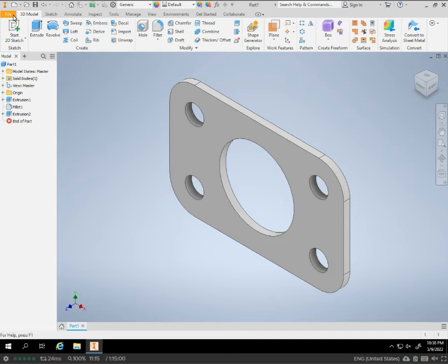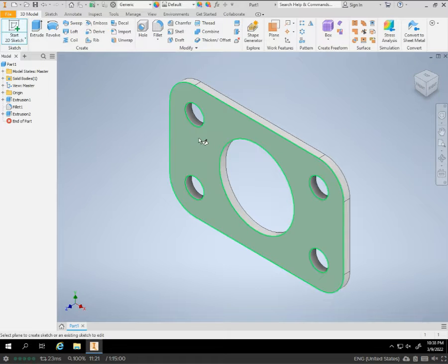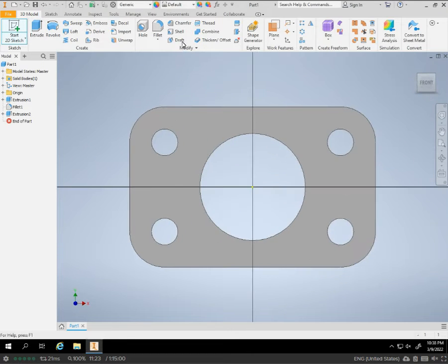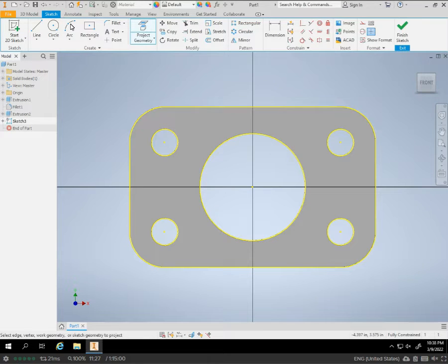All right. So now, next step, we're going to put the 2 slots in. So we're going to do sketch on the front face again. I'm going to use project geometry. And I'm going to do another circle, but I'm going to line up with this point, go down to this center, then do 0.75. I'm going to do the same thing on the opposite side.